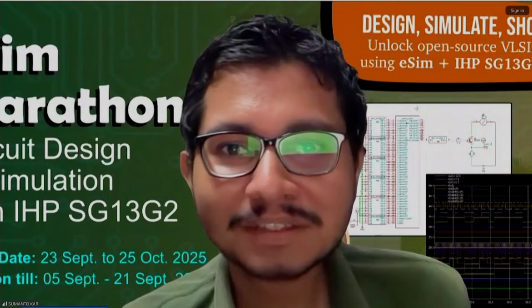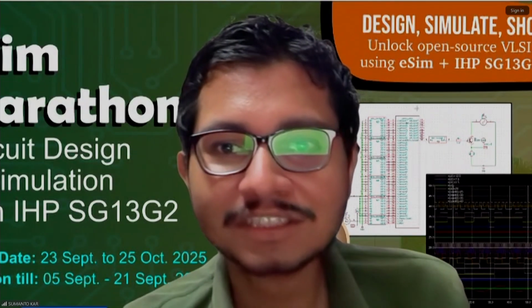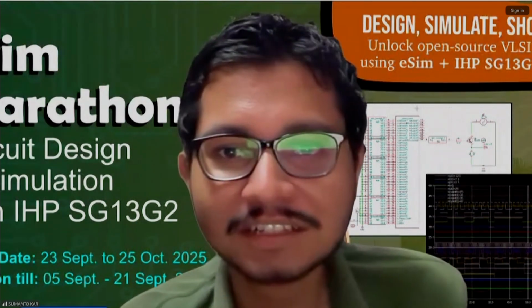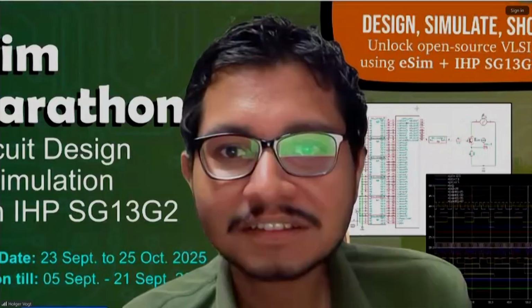Thank you. There is another question: how does Ngspice calculate the energy consumption or power dissipation in a given circuit? We calculate it from current and voltage. If you do a transient simulation, for example, you have currents and voltages continuously over time.